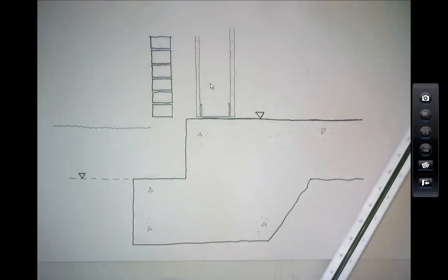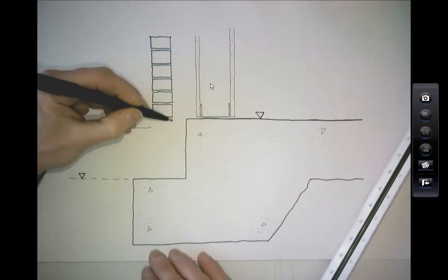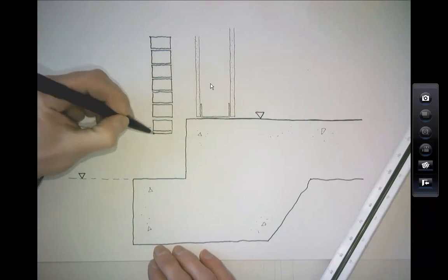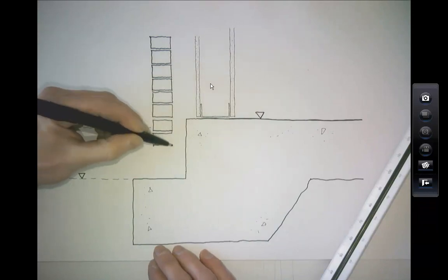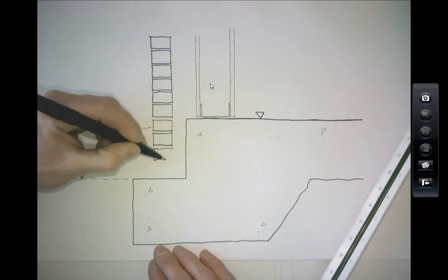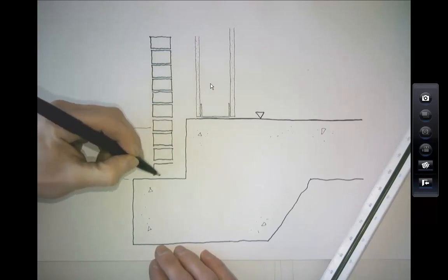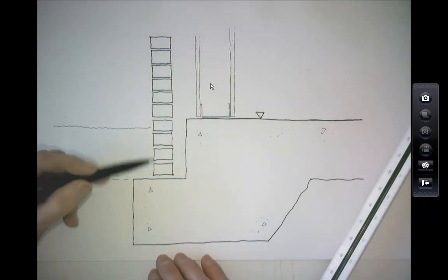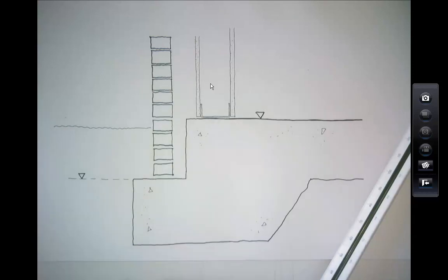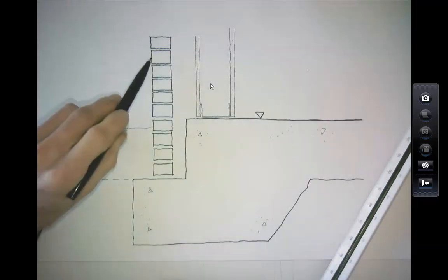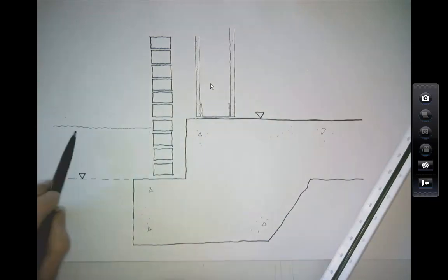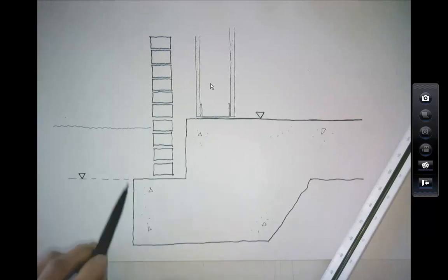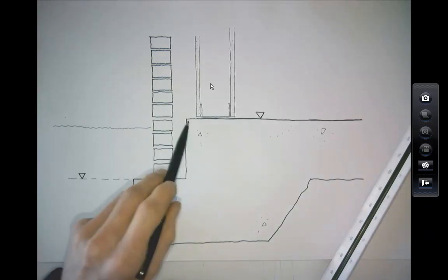And this level here needs to be on a brick dimension, because you're going to sit your bricks onto that. So I'm just going to draw my bricks down here, and I haven't measured it, so they may well not quite land. But you get the idea. That should have been on a brick dimension, so that brick nicely landed on that. So what we've achieved now is we've got our bricks coming down to the ground. They disappear into the ground, so we're not seeing that foundation. And we've achieved that by having this little toe on our slab edge.